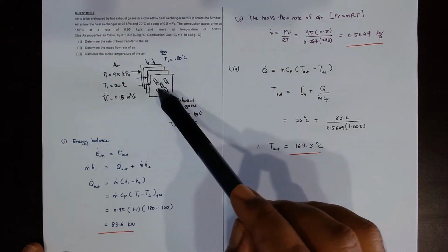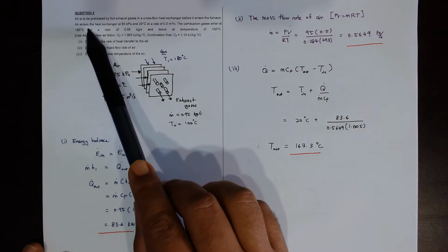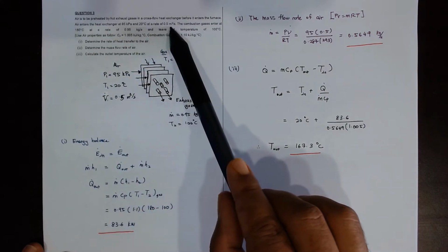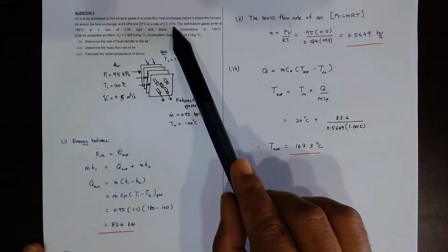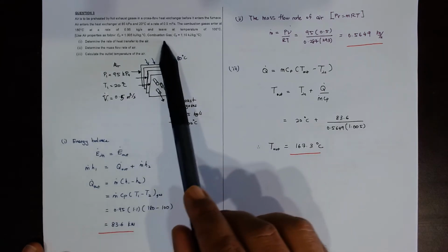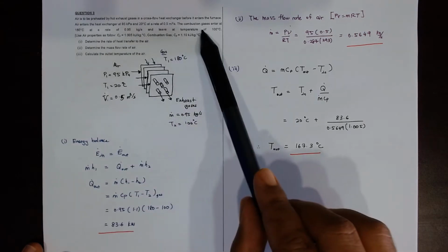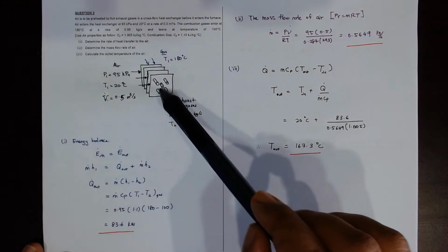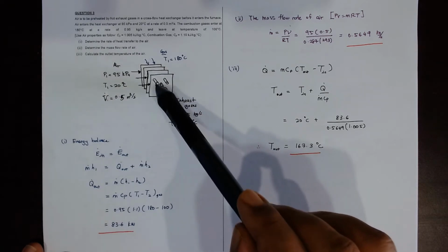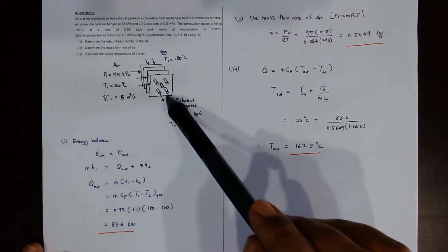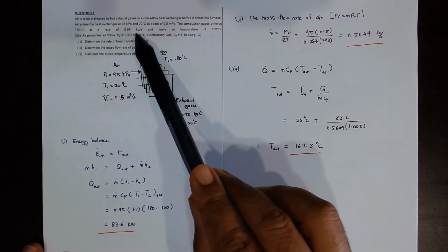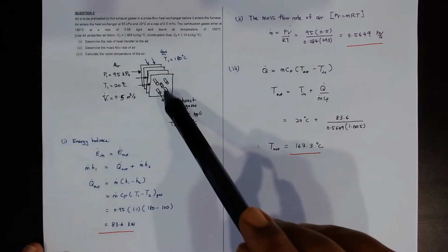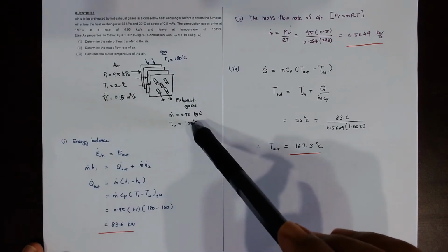Air enters the heat exchanger at 95 kilopascal and 220 degrees Celsius at a rate of 0.5 meter cube per second. So we have a gas throughout this piping system, illustrated at 0.95 kilogram per second, and it leaves at a temperature of 100 degree Celsius.